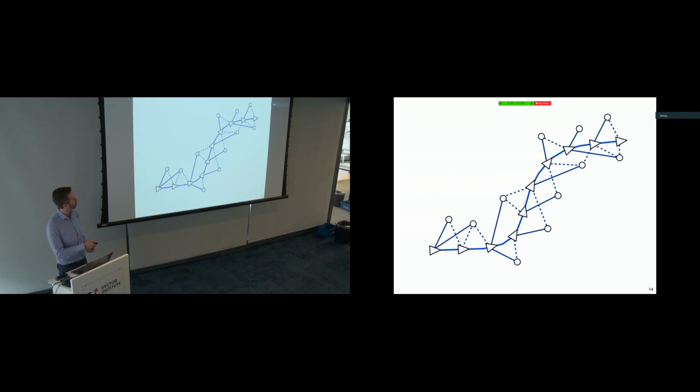And the idea is, as we're driving the robot to define one of these paths, it's being driven manually, and we're estimating our motion using visual odometry, in this case from a stereo camera. And so we can estimate the motion transforms between all of these edges, and we store those. And we also store the landmarks that we observe, in this case, something like triangulated SURF features. And this is critical. We store them relative to where they were first seen. We don't store them relative to some global reference frame. So by storing them where they were first seen, we have what's called a relative map structure. There's no privileged reference frame in which everything is expressed.